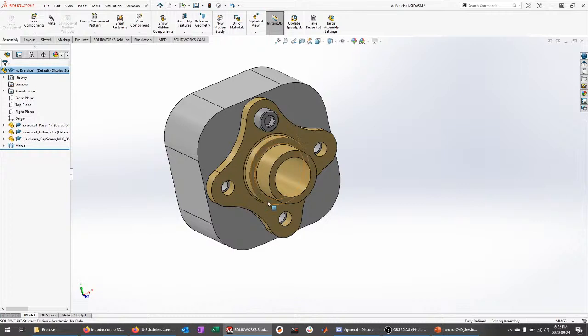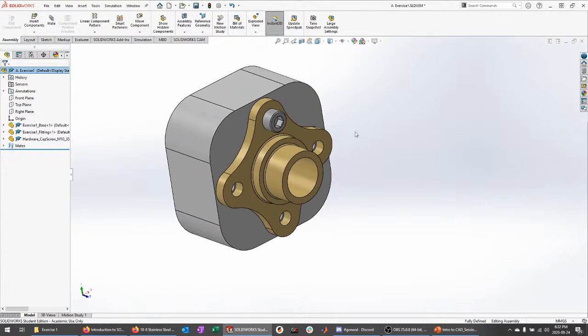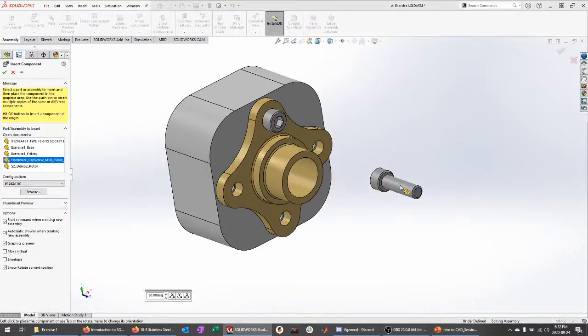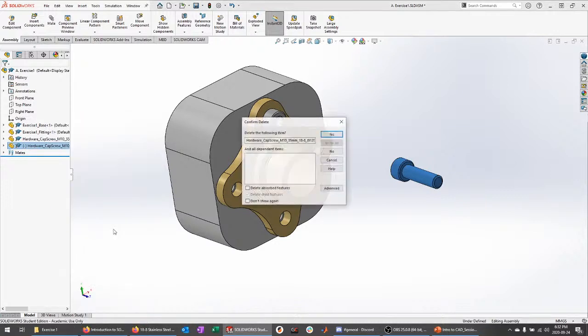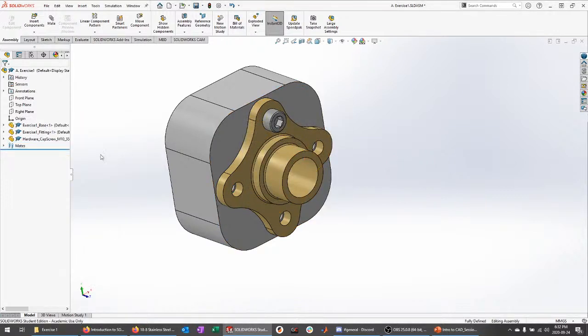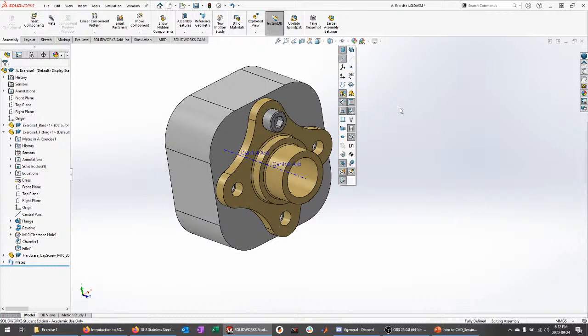All right. Now, in order to get the other three fasteners in here, we could just replicate exactly what we did just there. We can go, insert components, select that, place it, and then apply those constraints in the same way. But we're engineers. We're lazy. So actually, instead of doing that, there's a couple other ways to do this. So I believe if we hit the drop down on the fitting, there is an axis in there, and I'm going to make sure that our axis visibility is turned on. So again, that eye looking tool up here, hit view axes.